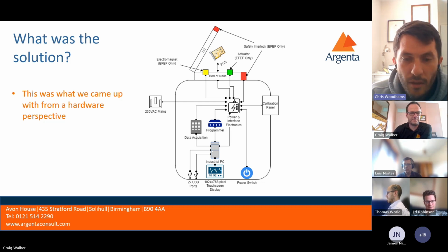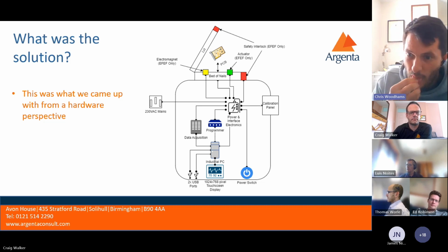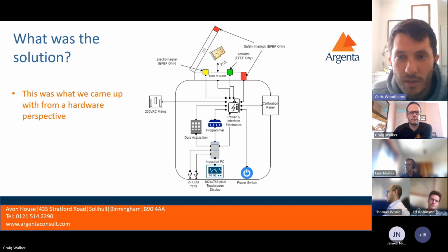So within the actual jig, we've just got an industrial PC which is connected to data acquisition, and a programmer which is used to send the software down to the microcontroller on the PCBs.